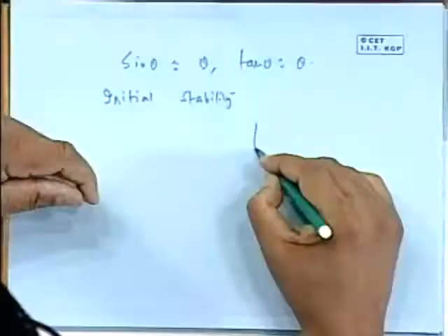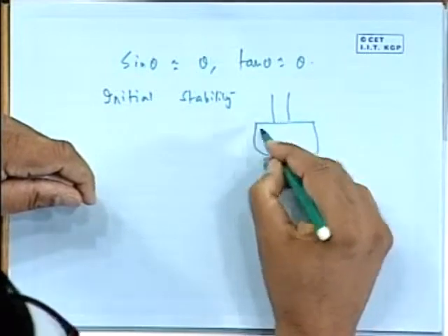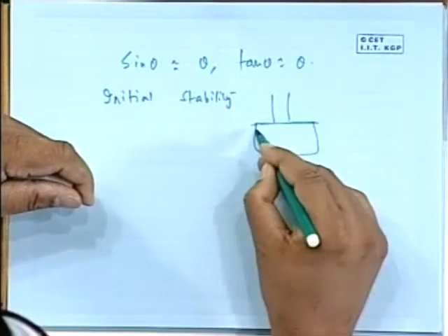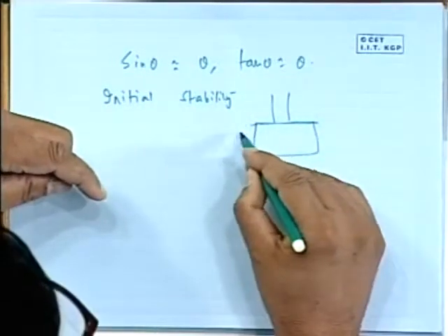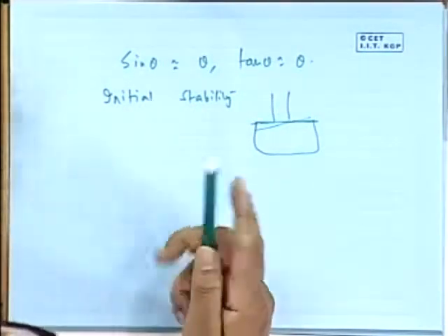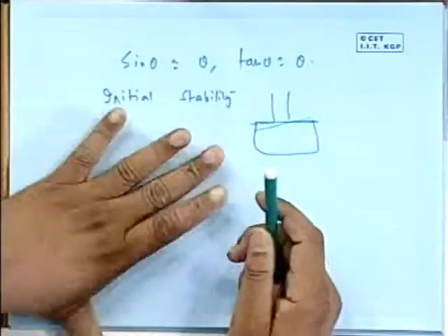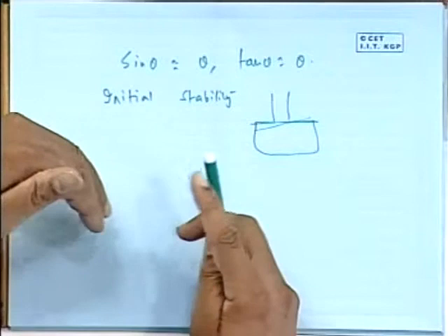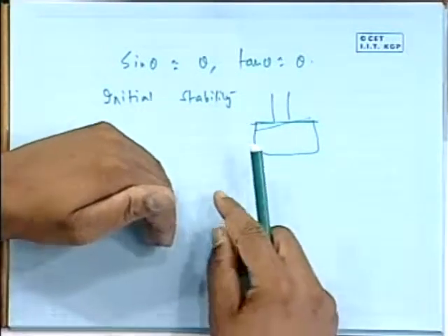This situation may come in some cases when the vessel or offshore structure is just inclined here. Then you know that if you take a small angle like 5 degrees, it will actually change the water plane. So strictly speaking, initial stability is concerned with a very small value of theta. We will in fact show now by a formula that the M location becomes independent of theta. That also is a confirmation that metacenter does not depend on theta as we define it.